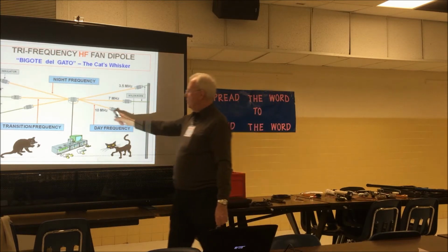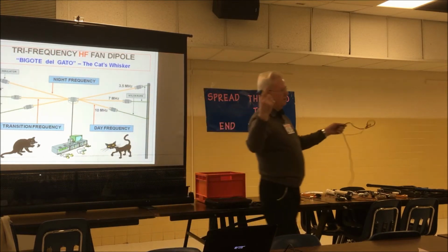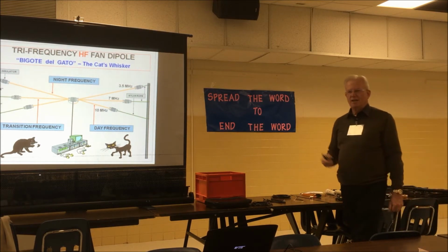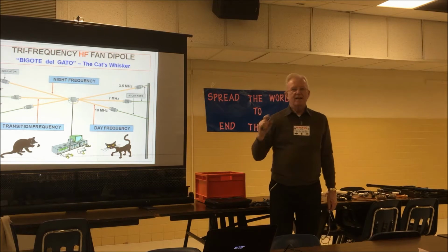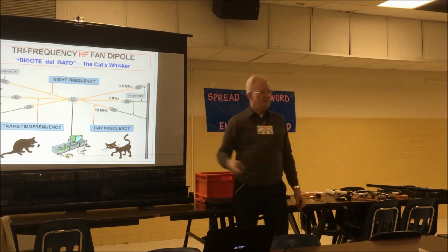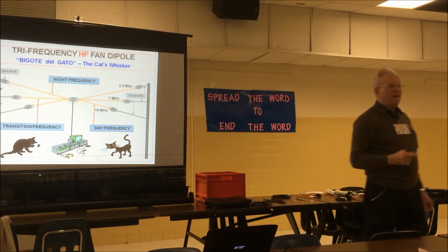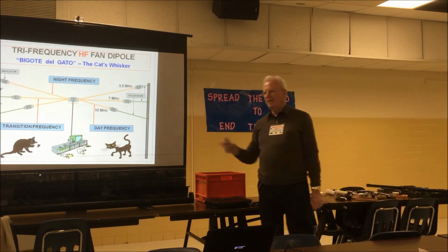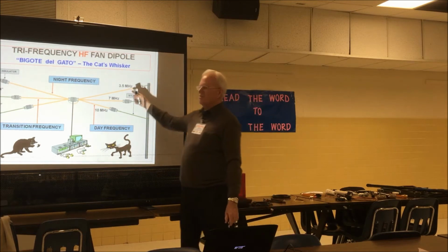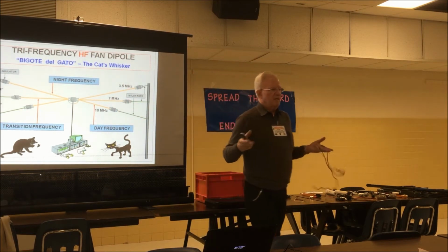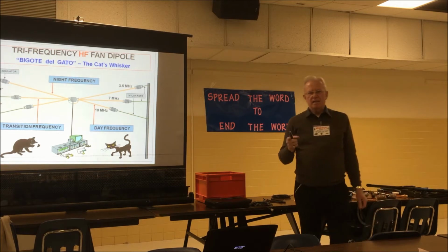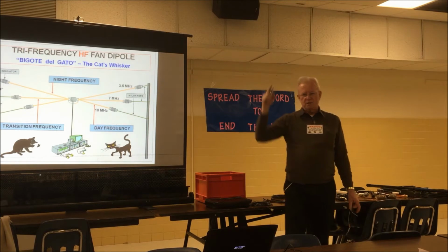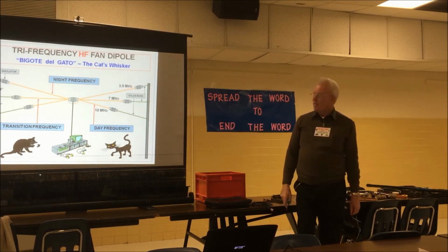7 megs goes up and looks at the 10 meg dipole, says, X sub C, too short, another 3,000 ohms. 7 megs goes up and looks at the 7 and goes, whoa, 50, that's just right. Path of least impedance. And it uses that antenna. Yes, there's a little reaction between the other two tuning it. Lee and I made one for field day a couple years ago. We were in his backyard for hours trying to get it right. We did.